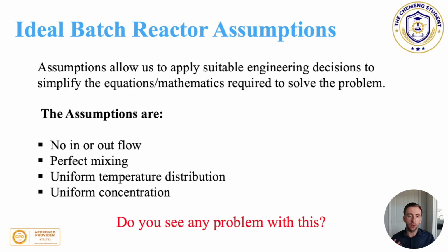So in our extensive reactor design course, we uncover things called a bypass and a dead zone that you have to account for if you want to design real industrial reactors, because these will have an adverse effect on the batch time, the conversion with respect to time, the residence time within the reactor for continuous systems, and so forth. That's what you would need if you wanted to design industrial scale reactors.